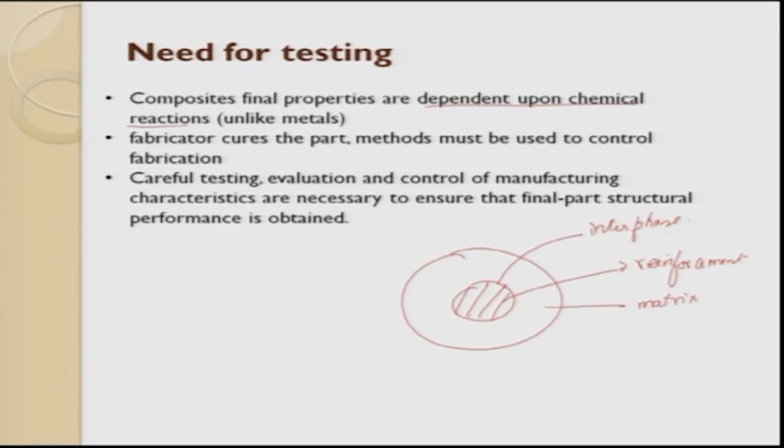If the interface is not properly formed, though the composite might look good, it will underperform when it is put in real time use. So there is always careful testing required, and it is not easy like metals. Here you are supposed to properly grip and then conduct your evaluation properly.